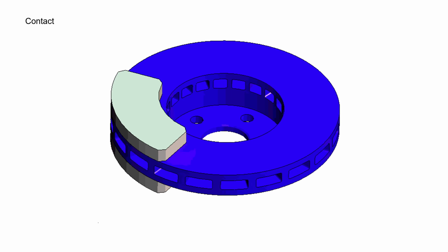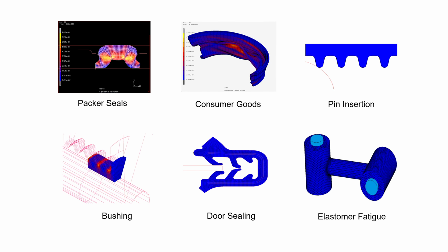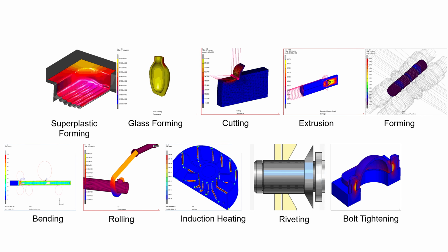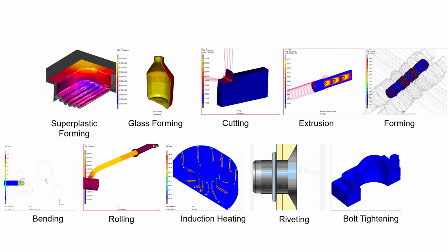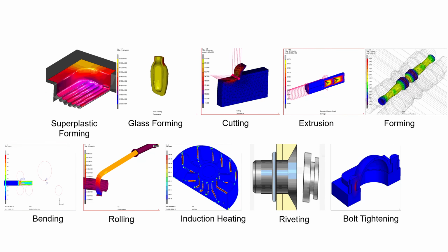Another source of nonlinearity is large deformation, especially if it leads to distortion of a shape, as we see here. And contact is a serious and challenging source of nonlinearity. Marc is often used in design of seals, and Marc can model the numerous manufacturing processes shown here. Note that Marc can integrate structural and thermal simulations.